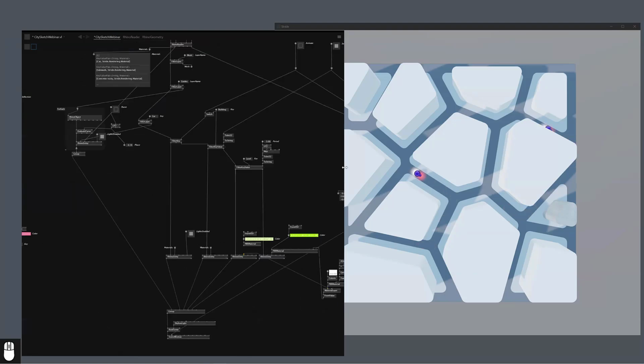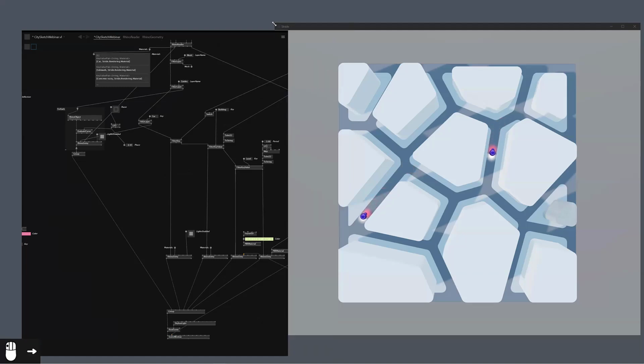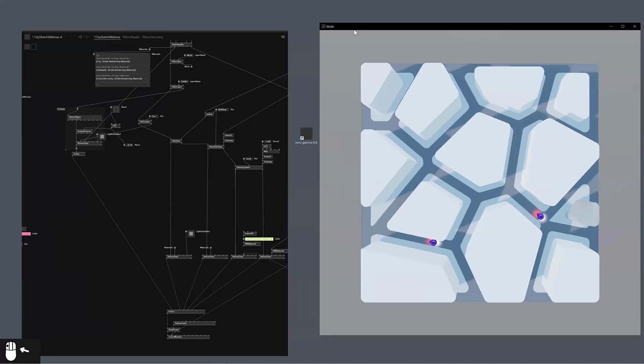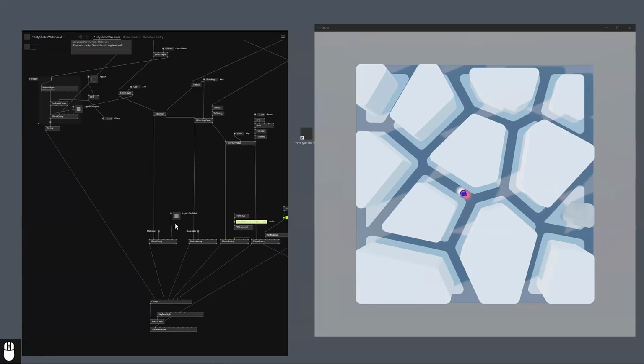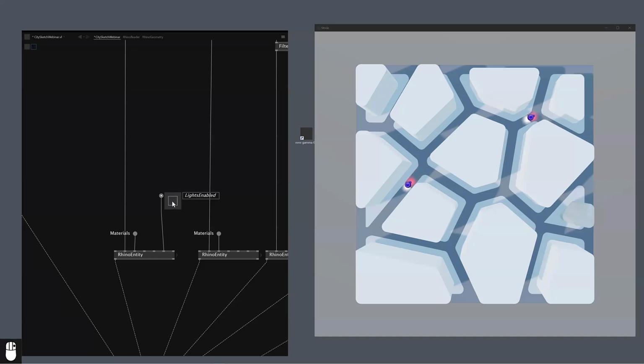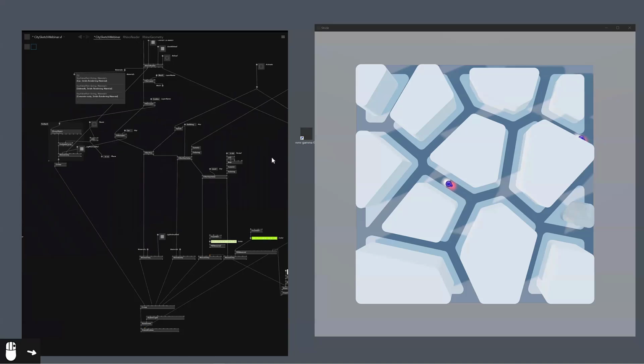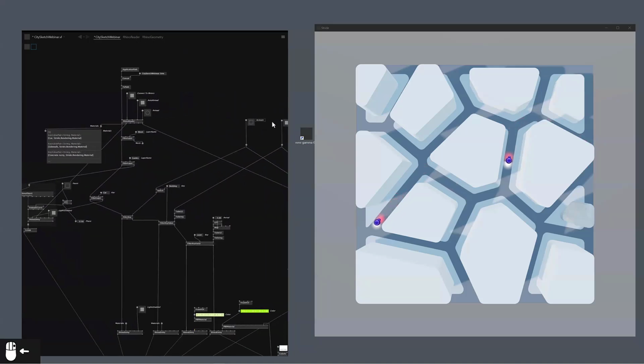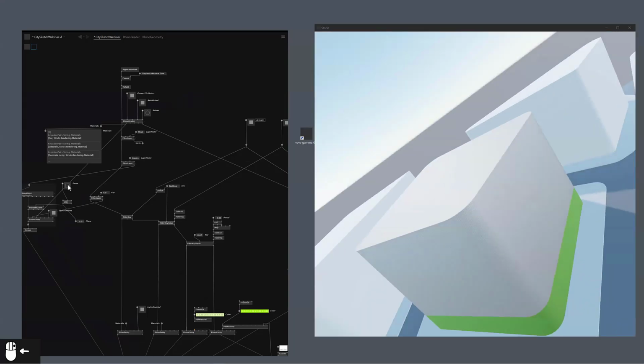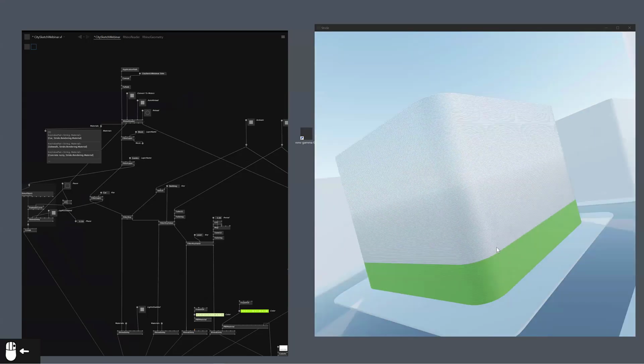So speaking of lights, not every light is possible to convert to V4. I'm working on this a bit, but also, I have a directional light in the scene. Here you see this happens sometimes, but if you have done it once, this will not happen again. And here you can see I can just turn the directional light I have in my scene on and off just with this selection if I want to enable my lights. So let's zoom in again and wait for the car to pass by. Stop. Okay, now we have our car.